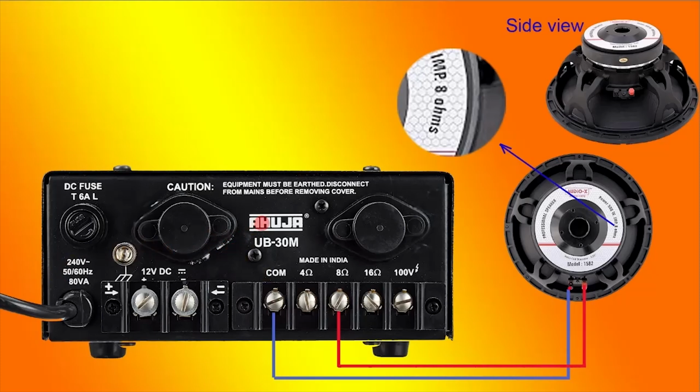Here we have connected one speaker to the output of this amplifier. You can see from the information written here that the impedance of this speaker is 8 ohms. That means maximum power will be delivered from this amplifier to the speaker when we connect this 8 ohm speaker to the 8 ohm output. See, this is the common point and this is the 8 ohm impedance.